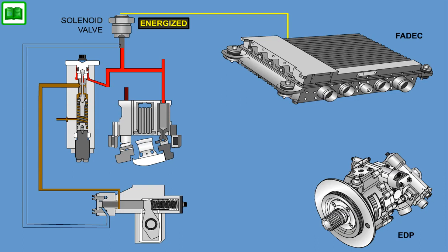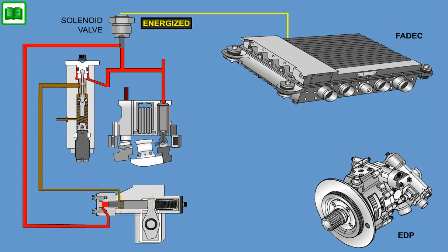With the depressurization valve de-energized, the engine-driven pump operates as a normal pressure-compensated variable displacement piston pump. When the depressurization valve is energized, the solenoid valve position shifts, resulting in pump discharge pressure being ported directly behind the auxiliary stroking piston, bypassing the compensator. With sufficient pressure applied across the auxiliary stroking piston area, the auxiliary piston pushes on the primary stroking piston, decreasing the hanger angle and reducing the pump outlet flow. Since the compensator is bypassed, the pump discharge pressure is reduced to the minimum pressure required to destroke the unit.